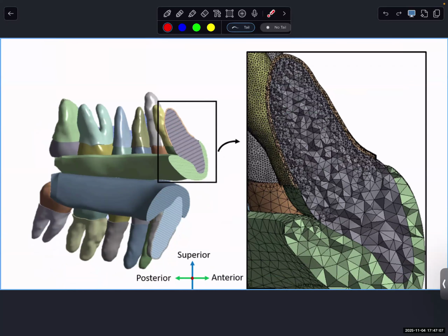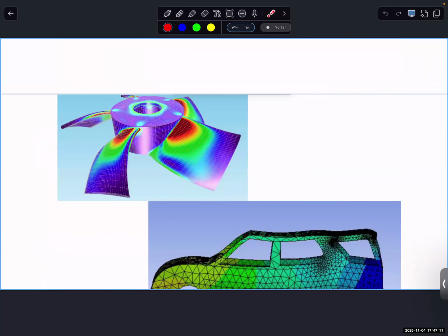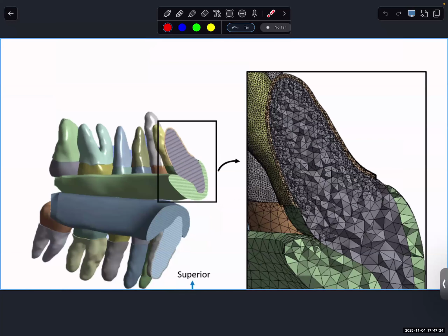So this is basically a solid model. As we talked about before, an STL file is a surface model and everything is in the surface model, so we can consider it a plane stress. There's no stress in the third direction. But for our simulation, we always need to use a 3D simulation. So now it becomes the tetrahedral element.